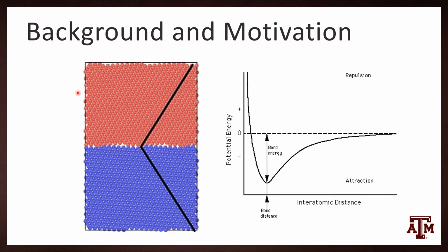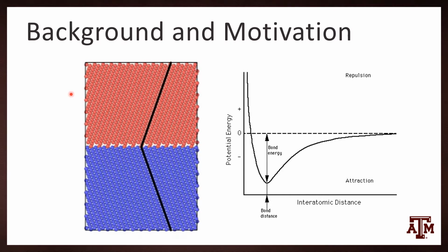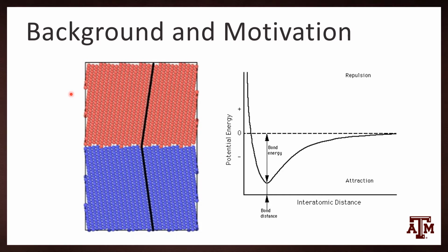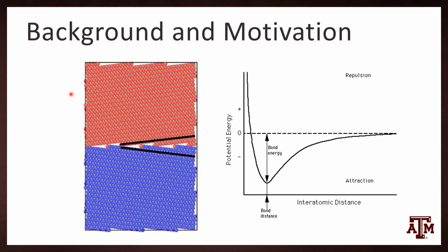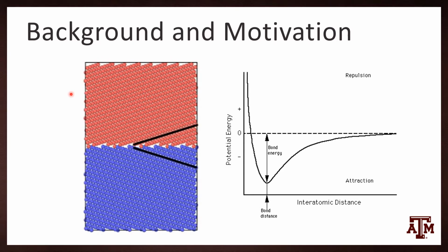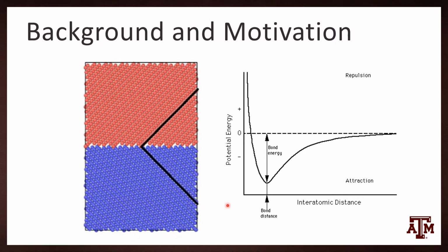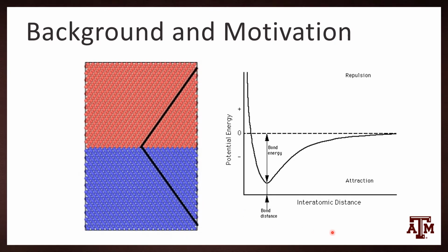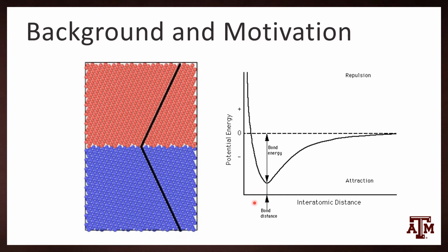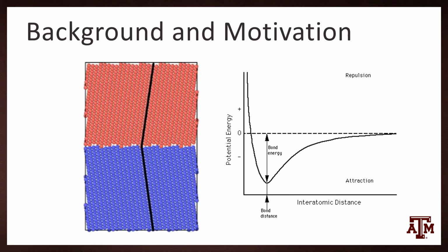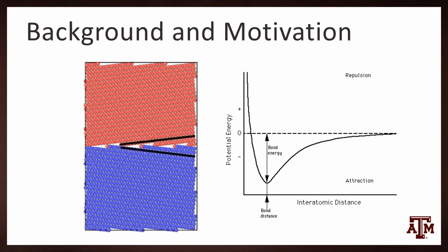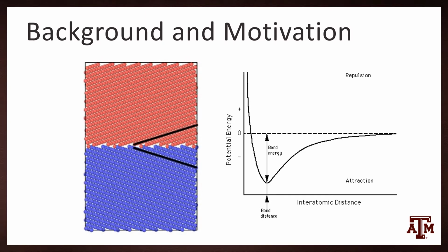The way that MD works is by tracking properties of every atom, like XYZ coordinates, velocity, temperature vibrations, and bonds between atoms at each time step. The simulation progresses through these very small time steps using bonding physics to calculate how atoms will shift around. This gives us insight at a nanoscale that we look to extrapolate upwards to understand phenomena at larger length scales